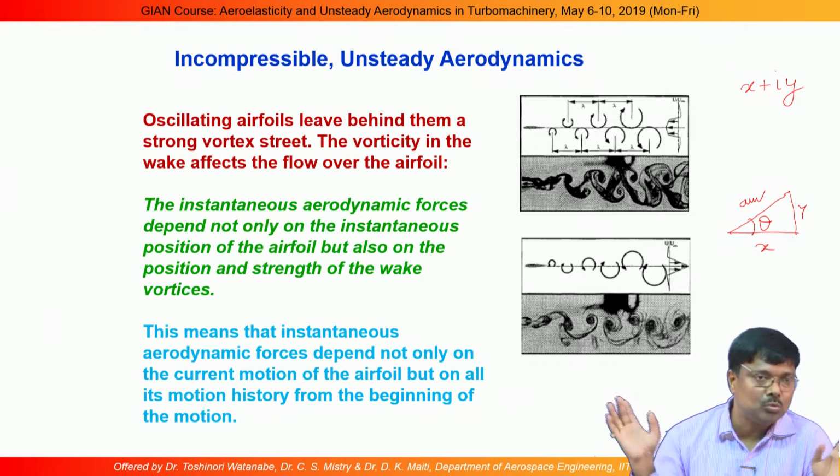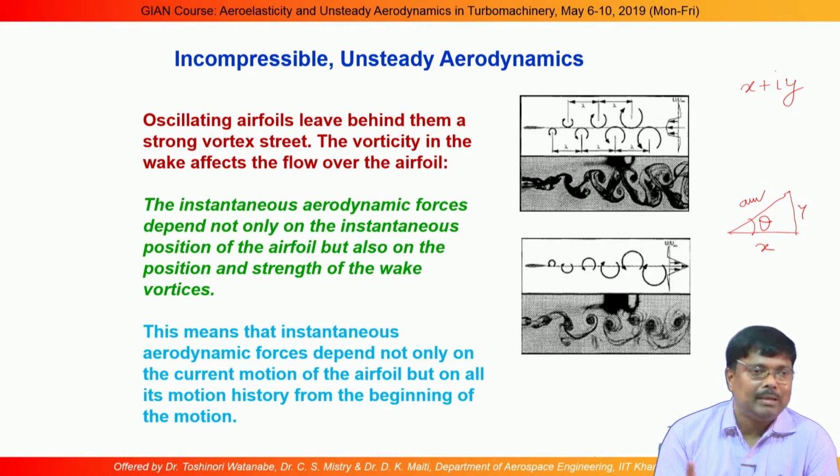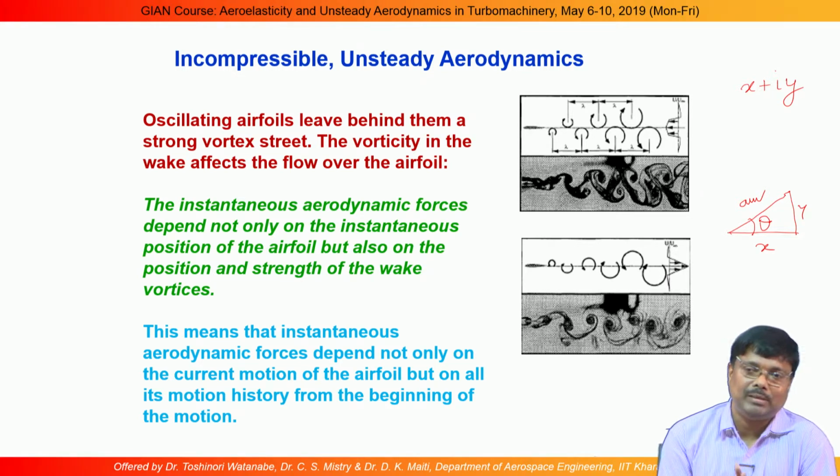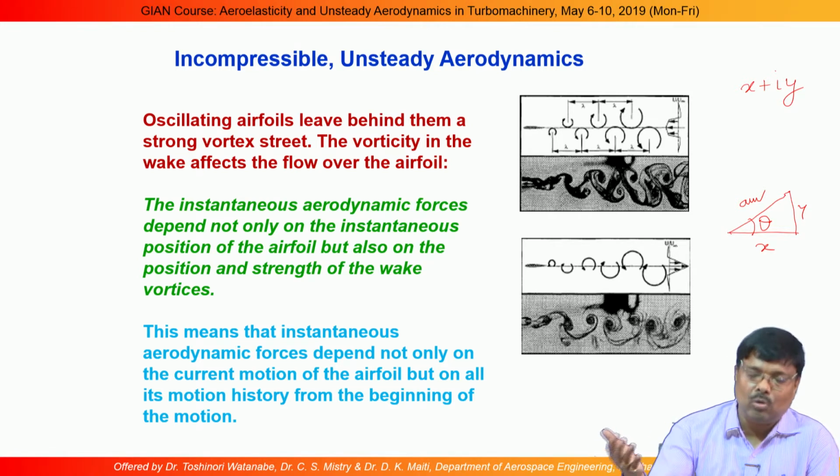You cannot go to high supersonic Mach number, because there are limitations, and obviously you will not find any code available for the transonic region. So, whatever calculation we make, it is some extrapolation from the subsonic aerodynamic load or interpolation, or the same extrapolation from the supersonic.